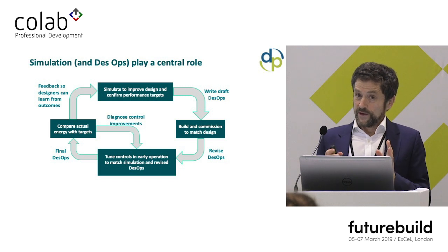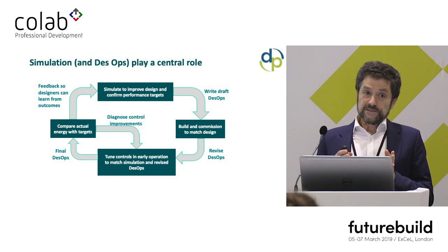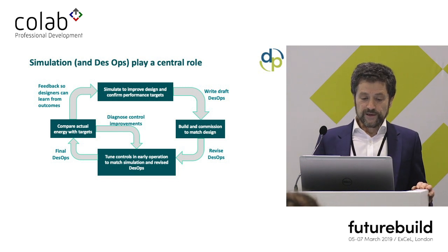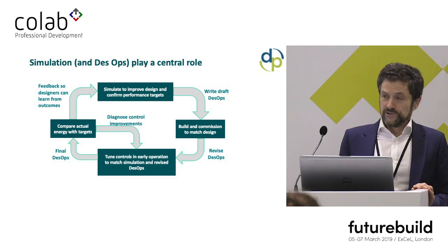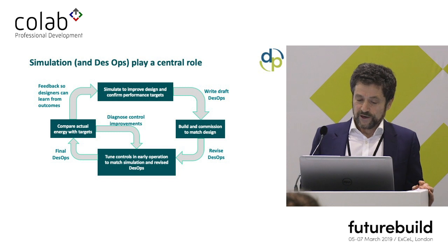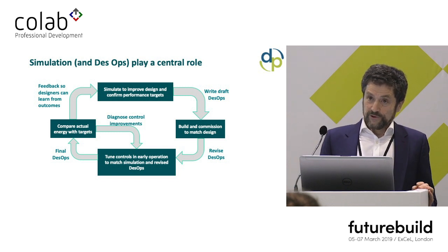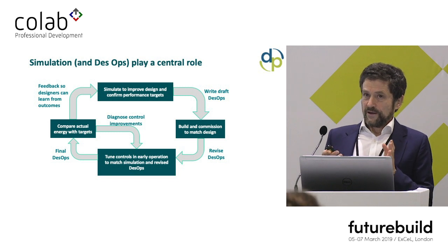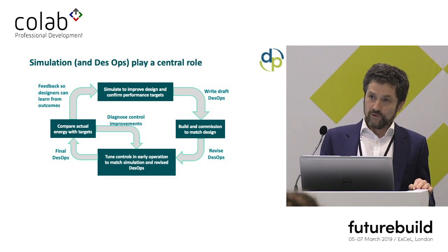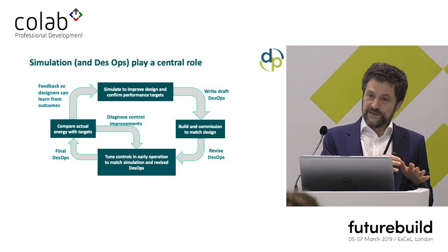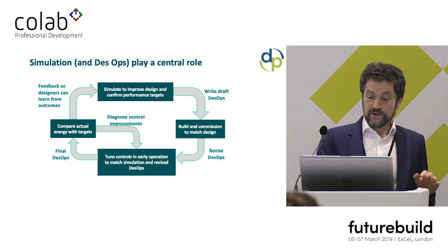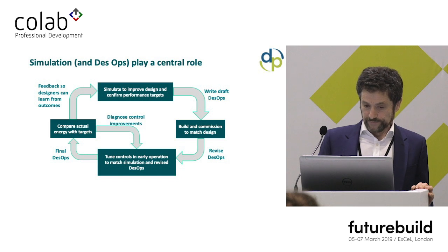And there is a process of looking at the sub-meter data for the building, checking how the real performance of this building compares with the predictions, diagnosing improvements or things that aren't working exactly, making sure that the building rating is on track to what it's supposed to be. So that gives you a flavour for how the modelling is such a key part of the whole process, running all the way through from potentially stage 2 right through to stage 7 of the process. It's not just a backroom compliance check that we do here.